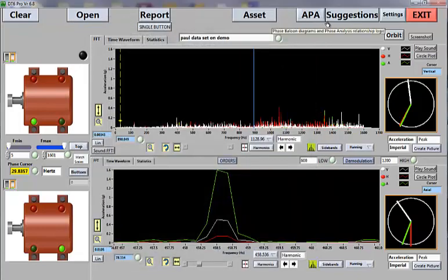One thing I will mention is you can hit this sound FFT button on any plot, or you can hit this play sound button, and there are two different ways of listening to the data so that you can actually hear if there's anything unusual about it. I won't click it now because it doesn't tend to work super well over Camtasia. It can't give you the sound that I can hear on my end, but you can press that button and actually hear your data and then watch an FFT as it moves along to see if there are any noticeable trends in it.